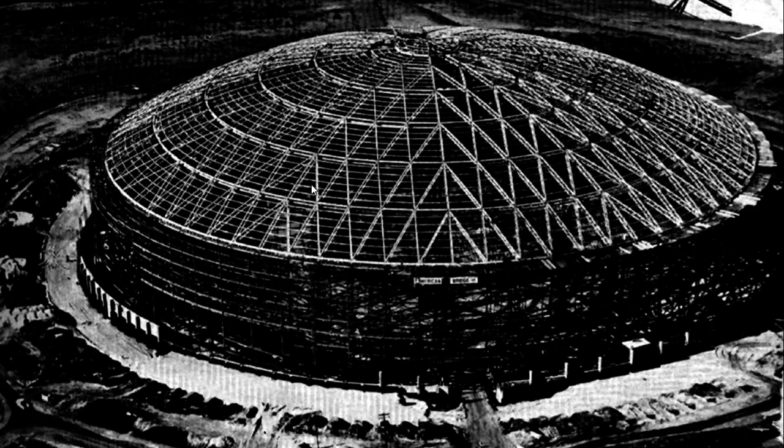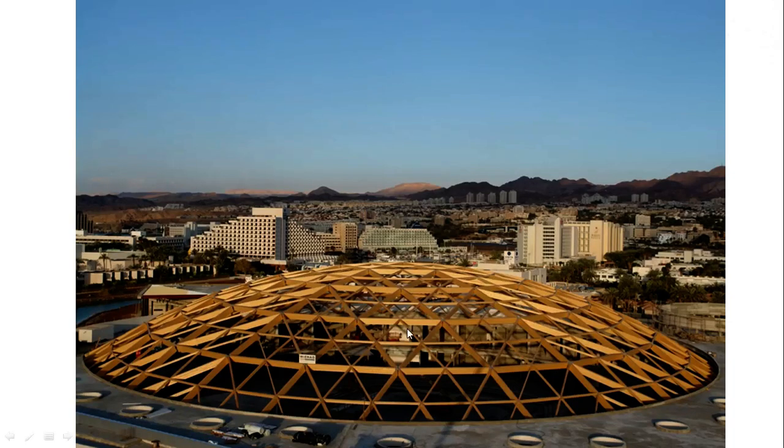You'll also see the principle that I've talked about many times now, that each of these ribs, whichever direction they're going in, is actually a truss. Well, it's been doubled, hasn't it? It's been doubled, so it's got a deep section. Can you just see? Each one is a truss of deep section. And that aids the overall strength of the dome.